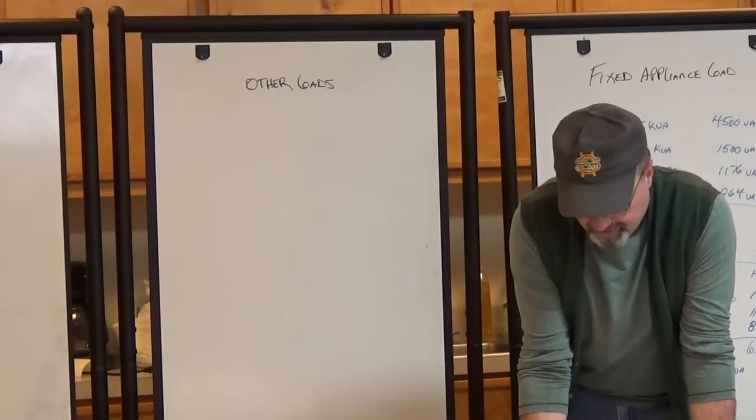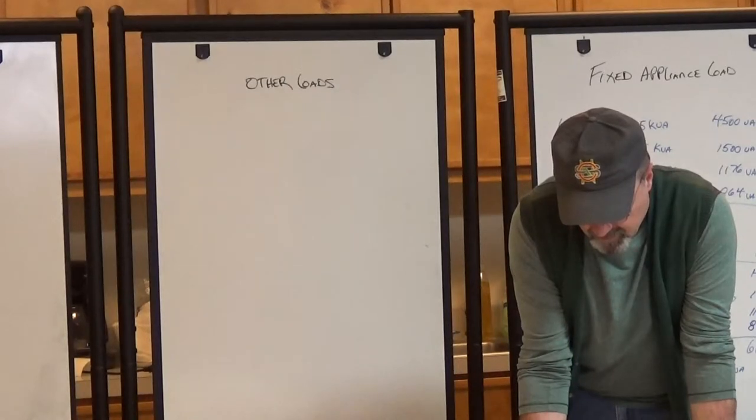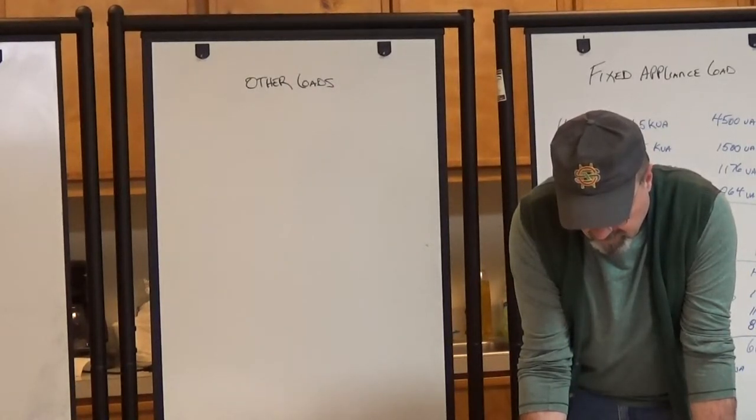In all occupancies, the minimum load for each outlet for general use receptacles and outlets not used for general illumination shall not be less than the calculated in 220.14(A) through (L), the loads shown being based on nominal branch circuit voltages. Okay.